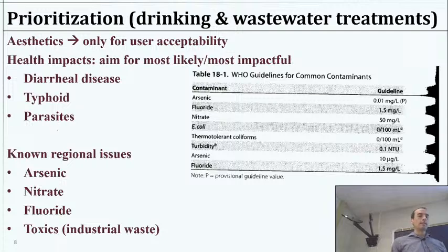Along that note, one of the easiest things to get rid of would be larger organisms, what we might call parasites. Parasite is a pretty loose term in water and hygiene kind of stuff. We sometimes refer to the microorganisms, Cryptosporidium, Giardia, and amoeba types, those eukaryotic large things, protozoa, as parasites. But we're also talking about hookworm and things like that. So certain things you could literally get rid of with a screen mesh, for example, that would have infected somebody, but you reduced the exposure or you physically removed it, and that was pretty easy to do. So that'd be a pretty simple one.